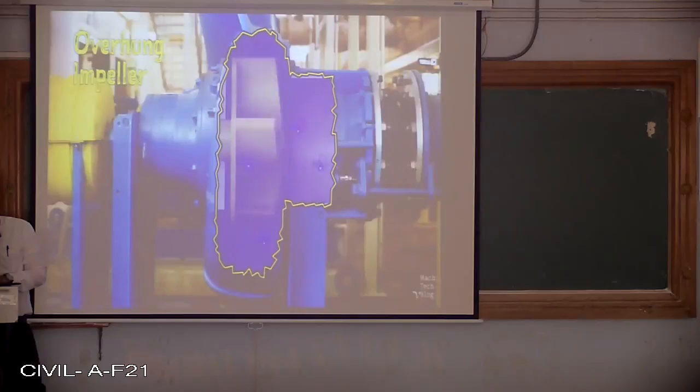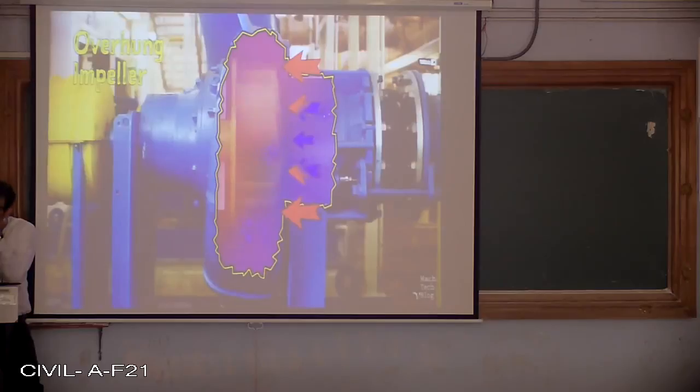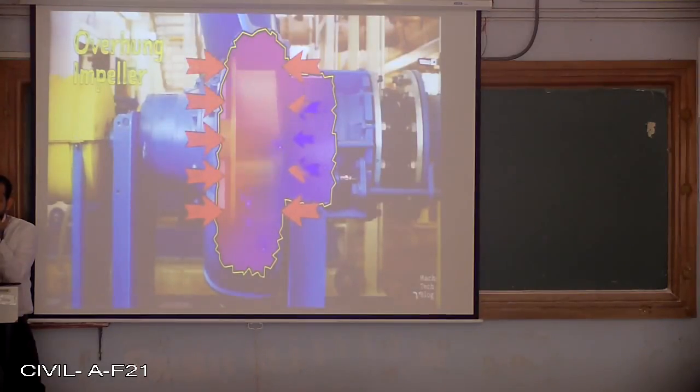During operation, there's a zone of low pressure at the suction eye where fluid first enters the impeller, and a zone of high pressure at the outside rim of the impeller where the energized fluid is released into the volute chamber. This high-pressure fluid also has a leak path to the backside of semi-closed and closed impellers, which totally throws off the balance of pressure.